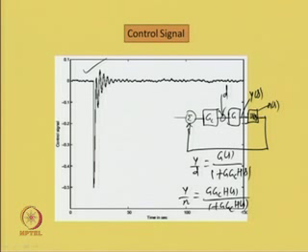So, if I look at the two transfer functions, what has to be done to minimize the effects of load disturbance responses, effects of static load inputs? If G GC HS is very high, a large number, in that case this will be 0. That is our aim, because we do not have to have any effect of static load disturbances D.